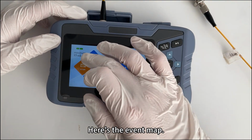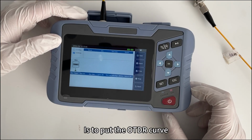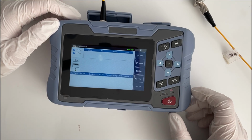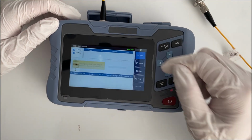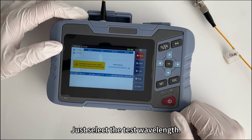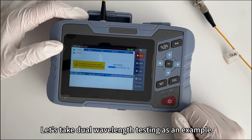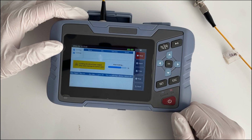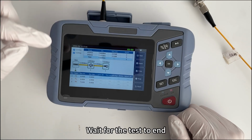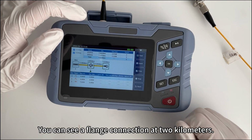Here's the event map. Event map is to put the OTDR curve. Display it graphically. Event mapping test: just select the test wavelength. Let's take dual wavelength testing as an example. Waiting for the test to end. You can see a flange connection at 2 kilometers.